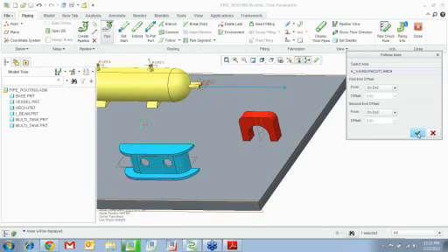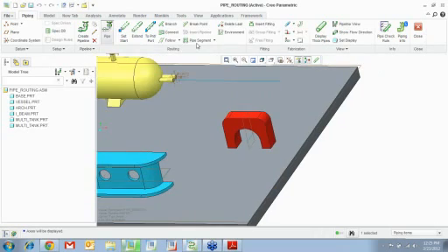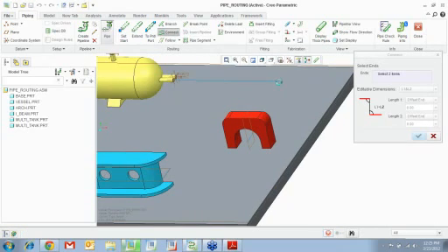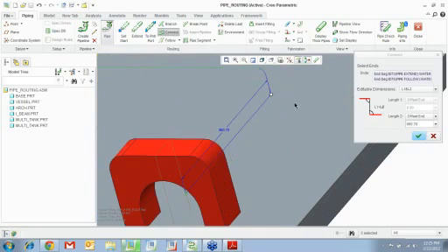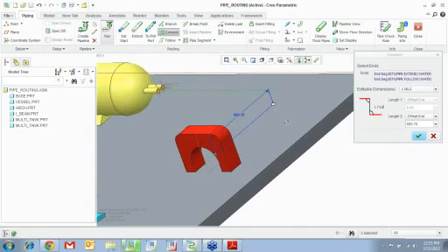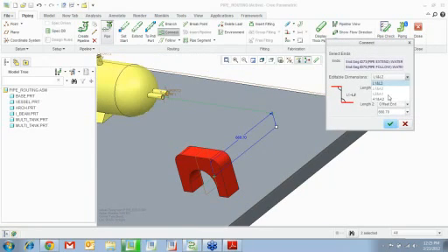See that? So the pipeline will be as long as the length of that axis. Now you have two pipelines and you want to connect them. So you go connect that to connect here. See that? So you see by default it's going to add your bends. Right? Now you can say I want to control it by the length, or you can say I want to control it by the angles.